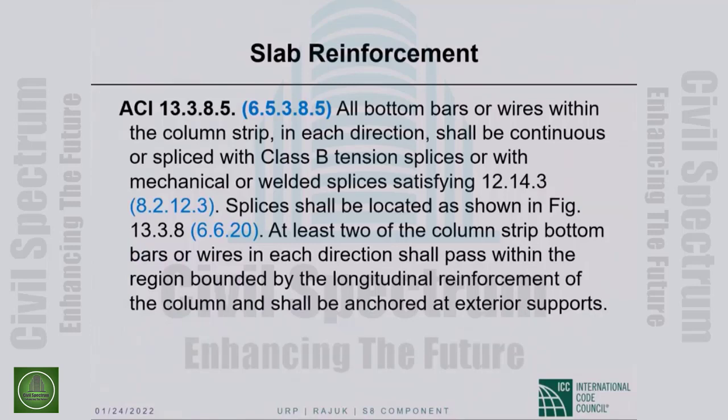Okay. This is, I think, rather different from everything else that we are discussing in connection with slab reinforcement. This is what we call structural integrity reinforcement. The idea is if there is extraordinary loading or a column gets knocked out or something, the slab should keep on hanging in place.